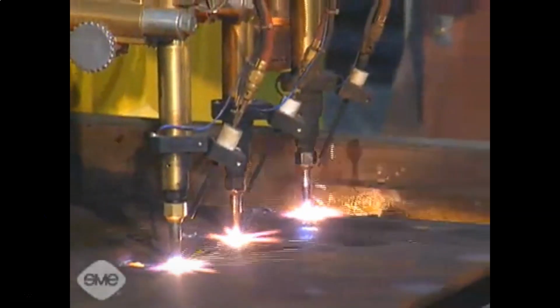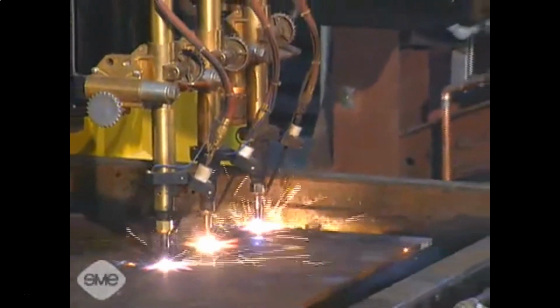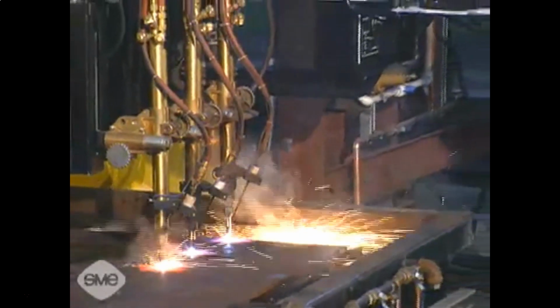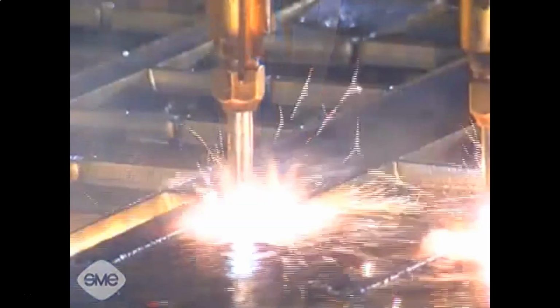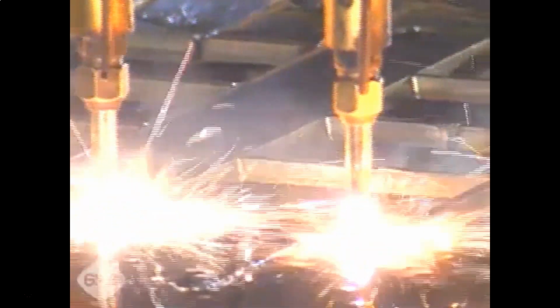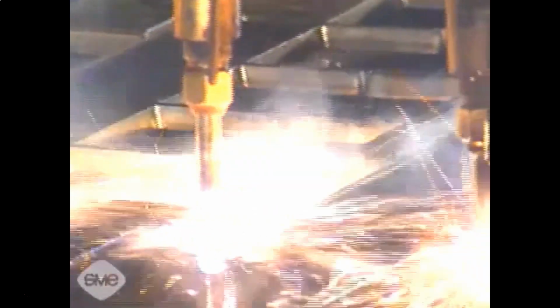Oxygen fuel, or Oxy-Fuel cutting, was once the only form of thermal cutting. The Oxy-Fuel cutting process uses a two-part torch, a preheating exterior oxy-fuel flame, and a jet of oxygen with a purity of 99.5% or better at the center. The cutting relies on a chemical reaction between oxygen and iron or carbon steel in the presence of heat.